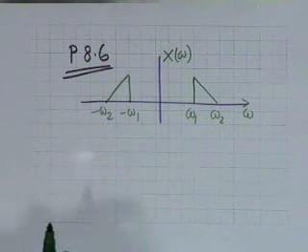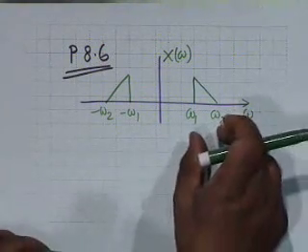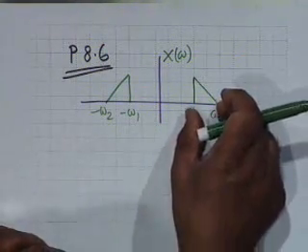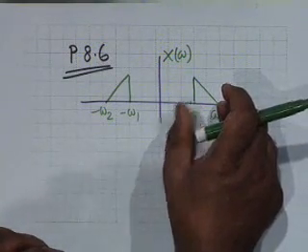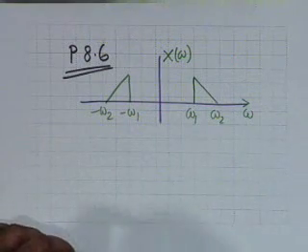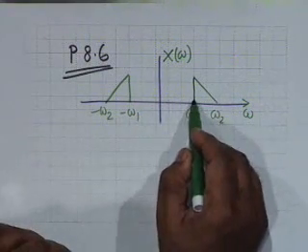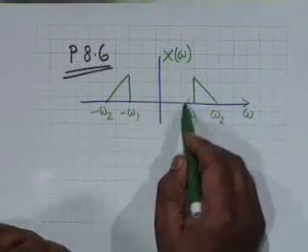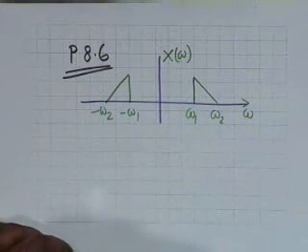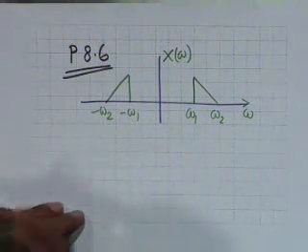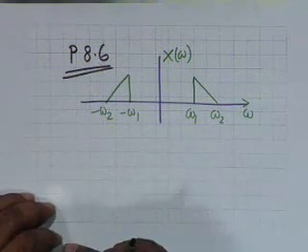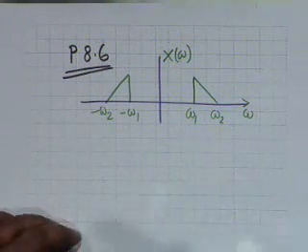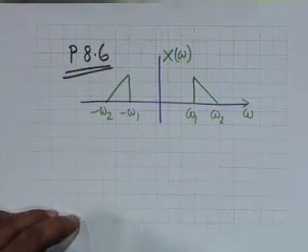And it appears unfair that for a signal whose energy is concentrated between omega 1 and omega 2, a rather narrow band, you require such a large sampling frequency, because all this is blank. There is no energy of the signal here. It appears therefore justified to at least qualitatively predict that perhaps a lower sampling frequency should do, and indeed it does, as we shall see now.